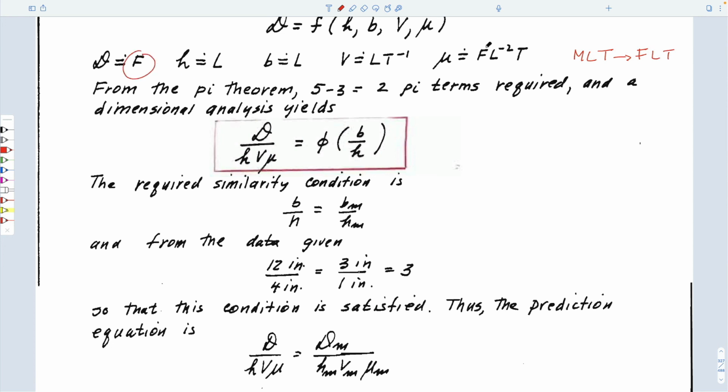So for forces, viscosity is newtons per meter squared seconds, Pascal seconds, right? So it's much easier to do the units, right? You know for sure that viscosity is in Pascal seconds, which is going to be in units of newtons, force, which is newtons, pascals per meter squared, length to the minus 2 times time, which is exactly what this is. So you don't have to mess around with mass for this particular one, but you end up with similar variables.